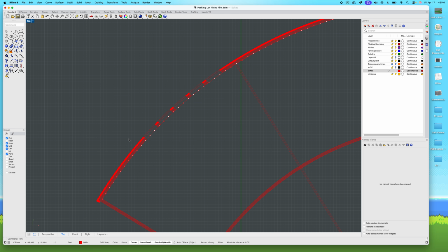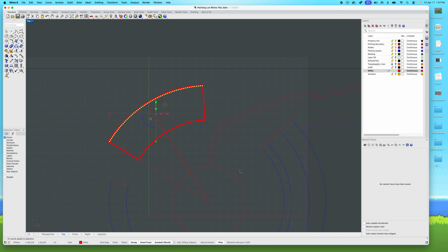One thing I like to express that has saved me hours of time is this wonderful filter tool right here. For instance, you see all these points. I don't want to take these points into Illustrator, so I'm going to disable my filter. I'm going to select only points, and so what you click on is essentially what it'll only select, which is fantastic because I've got a lot in there, and I just want the points out. Voila. So again, I can't express how great filter is, and I know I'm going extremely fast. Again, it is recorded, so feel free to pause the video and see what I'm clicking on and things like that.